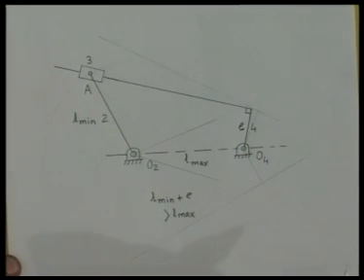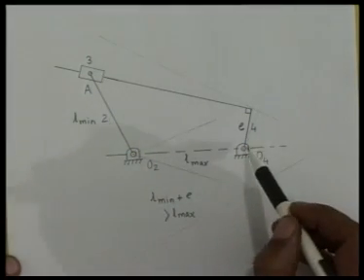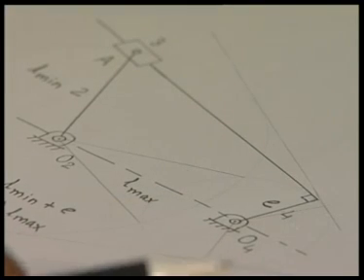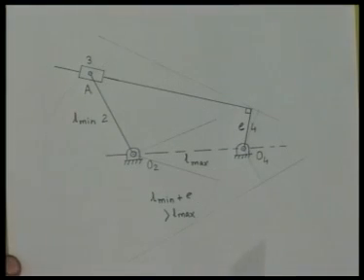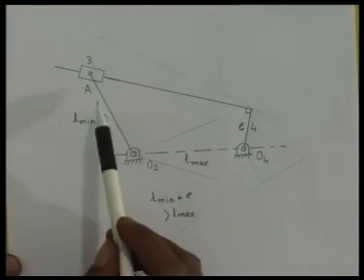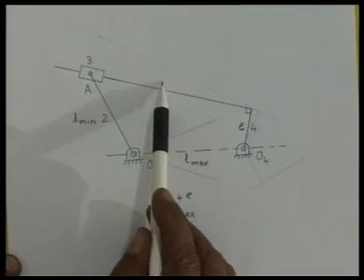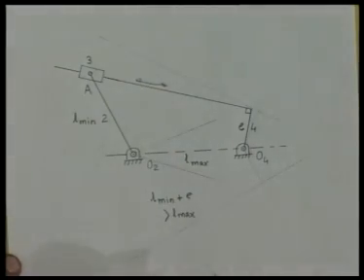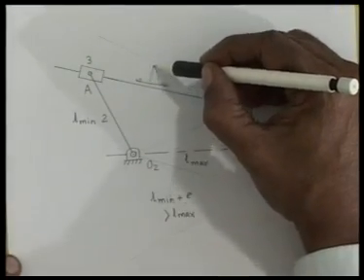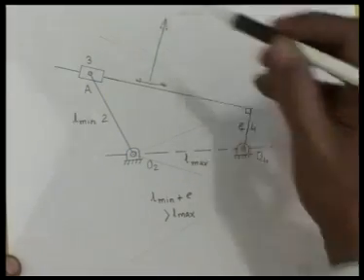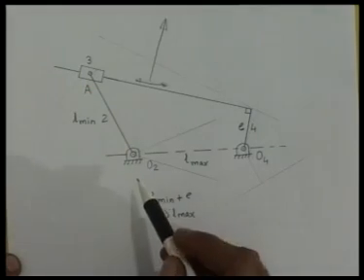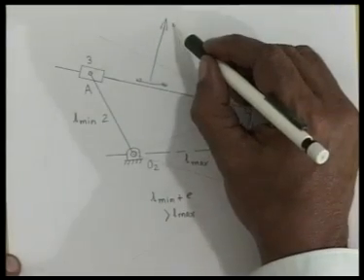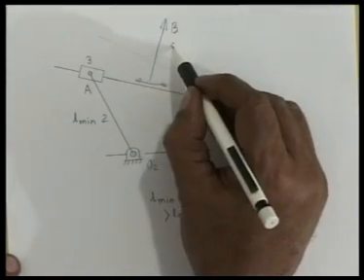and we have to find the angle through which the link O2A and link 4, that is this line, can oscillate. To solve this problem, let us imagine the equivalent 4R mechanism. That is, the prismatic pair between link 3 and 4 in this direction, let us replace it by a revolute pair at infinity in a direction perpendicular to this direction of sliding. That is, the hinge B of the O2A BO4, which is the equivalent 4R linkage, B is on this line at infinity.